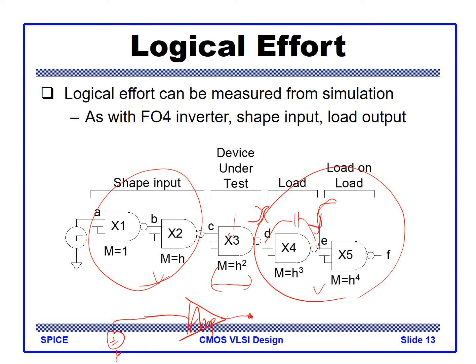You must use a practical input resistance, because the previous driving amplifier will have a finite output resistance, so you have to put some resistance there with the signal coming in.